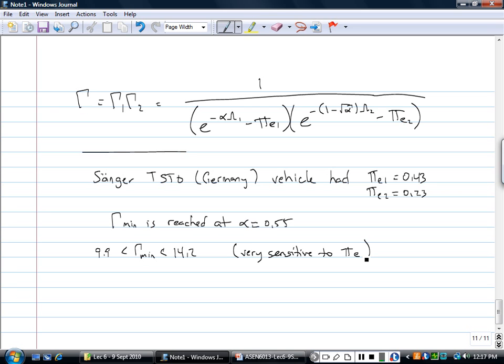What you're seeing here in everything we've done is that we derived a lot of equations for fuel mass fraction. Sorry, we're a couple minutes over, so we'll wrap it up. A lot of the analysis hinges back to the empty mass fraction. That mass dictates everything else. We spend a lot of time talking about empty masses relative to fuel masses, and then we get payload as 1 minus the fuel and the empty. So all of our performance parameters boil down to three mass terms, which is a really interesting way to think about it.